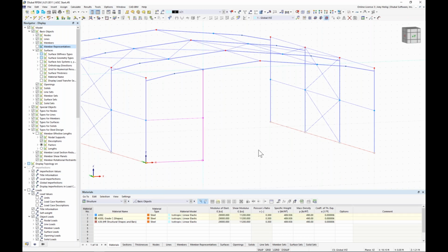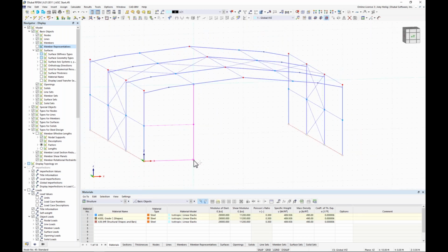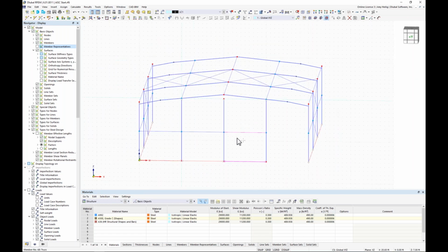I can take all of these elements and make additional copies here for the front of the structure. And I'll go ahead and take these two final elements, hold down my Control key to make my last copy. Now up here, we do need to connect this column up to the node. So we just drag and drop and everything is complete at the front of our structure. Now I'm going to highlight all of these elements here, including the nodes, the rigid elements down at the bottom.